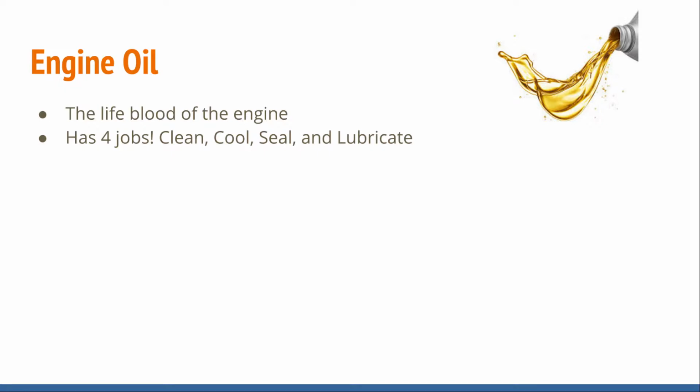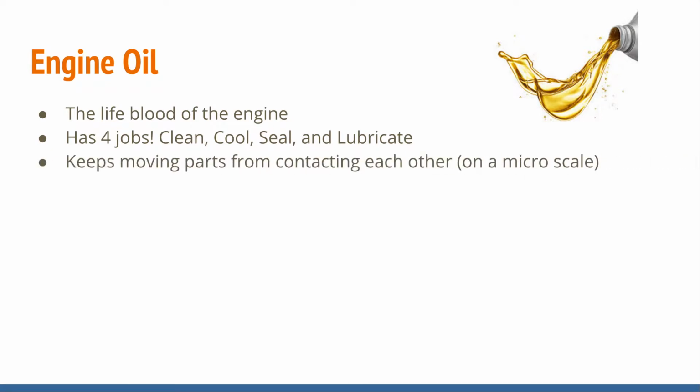There's actually a compression test you can do, a wet versus a dry compression test, and you'll be amazed at how much a little oil helps those piston rings seal. So the engine relies on that to seal. The piston rings rely on the oil. Finally, lubricate. When I say lubricate, it actually keeps the moving parts from contacting each other on a micro scale.